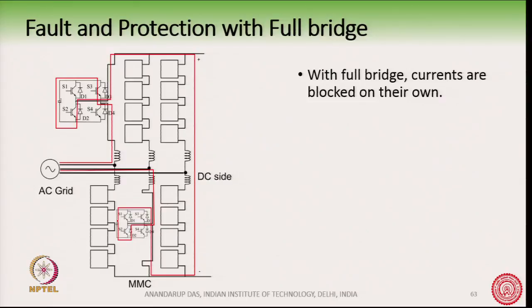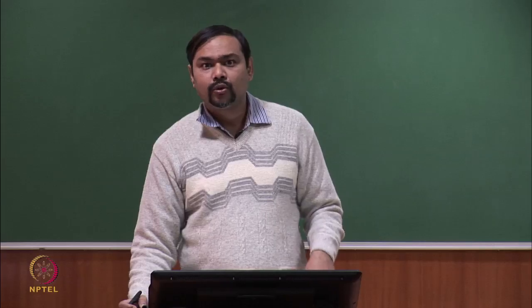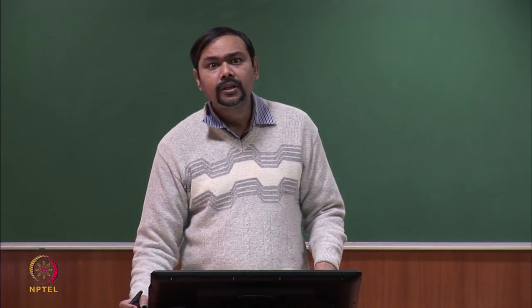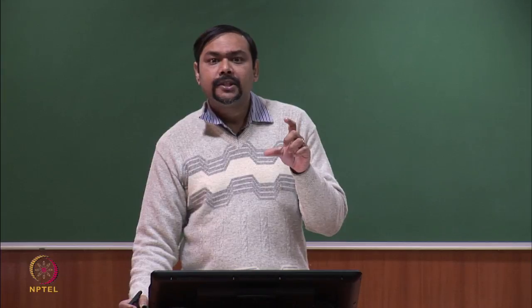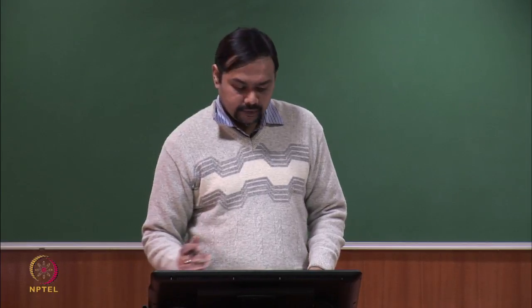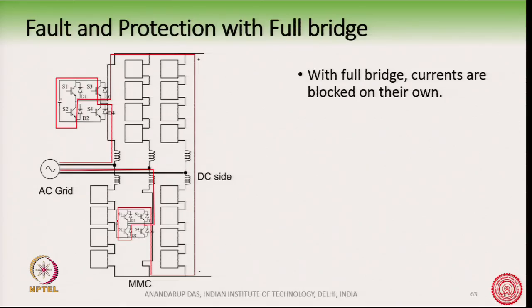And these capacitors are very helpful, because when the fault condition happens, during that transient portion before the circuit breaker opens, these capacitors which are in the path of the fault current will immediately charge up,